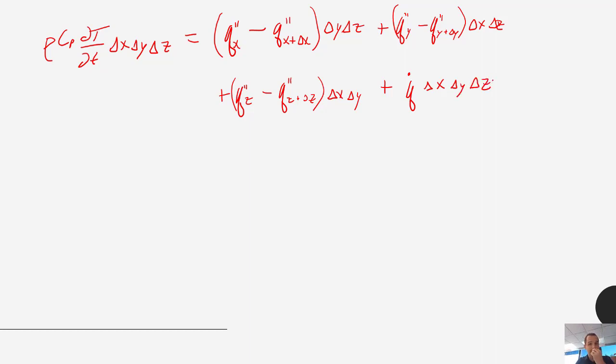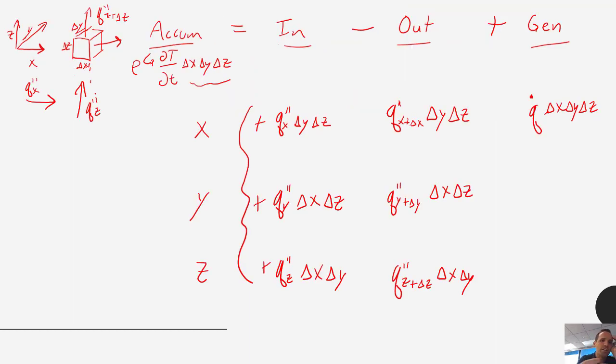So far this is just an energy balance, and it's actually still fairly simple. And we could actually go through and check the units on all of this. Here we'd have flux in watts per meter squared multiplied by two different distances, so that would give us meters squared, so overall we'd have watts. Here we have watts per meter cubed multiplied by a volume, so we'd get watts there too. And it's a little more involved for the accumulation term, but not so bad, but that ends up being in watts as well.